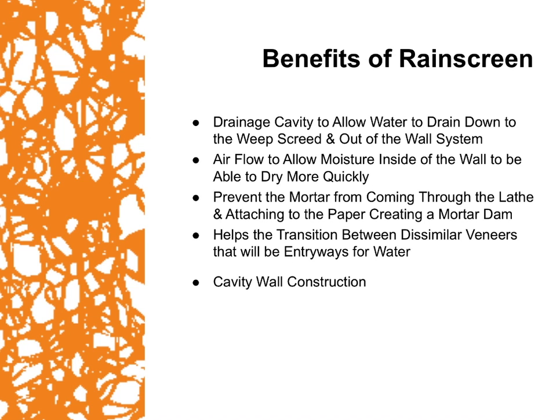Back when we didn't have any air barriers, any blown-in insulation, or any continuous insulation outside the building, and we didn't have tight windows and doors, our buildings and structures were very leaky. They unfortunately used up a lot of energy, but that energy passed through the structure, leaking through the outside. That helped dry our walls and keep them dry. That's why we don't see as many moisture problems in the past.